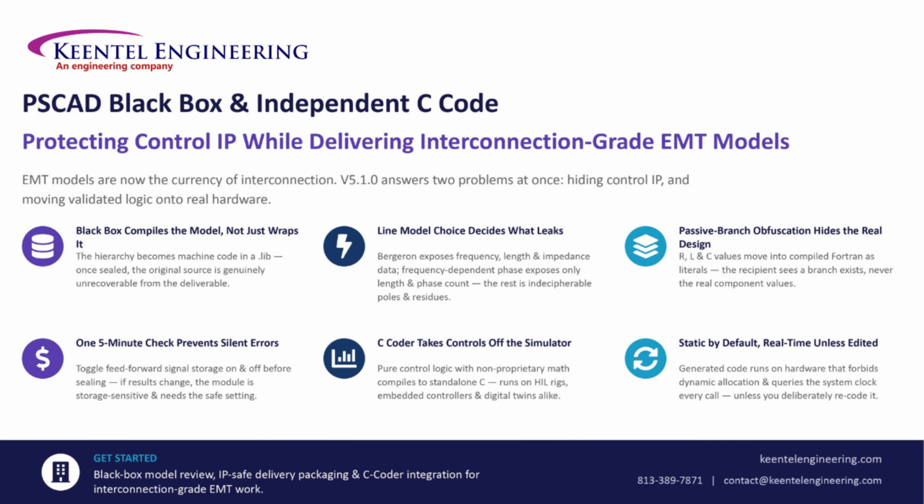EMT models are now the currency of interconnection, and PSCAD's V5.1.0 solves two real problems. Black Box compiles a control module into machine code. The original source becomes genuinely unrecoverable, while passive branches stay hidden and the model runs exactly the same. Independent C code does the opposite. It takes validated control logic out of the simulator entirely, compiling to standalone C that runs on real hardware, from HIL rigs to embedded controllers.